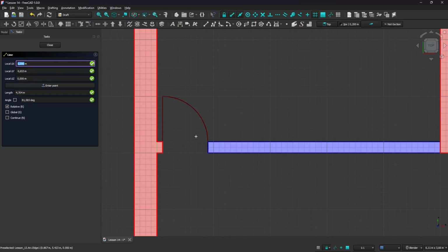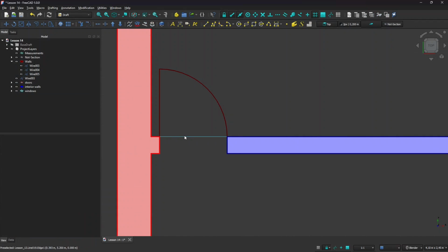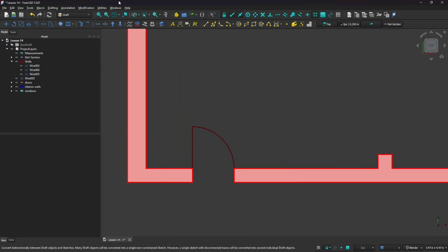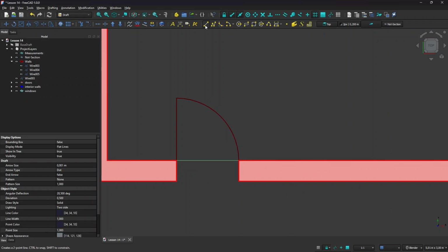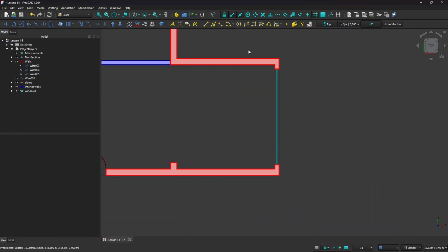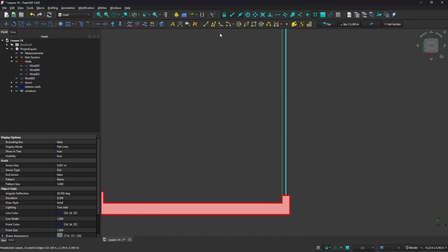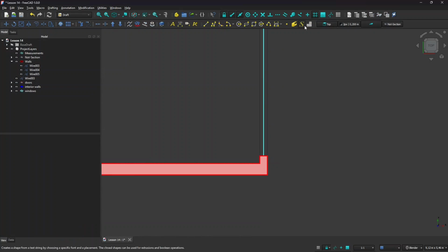And also here, if you change the material of the ground, you need to change here also with the line. So you can also use a hatch here and another hatch here, or a fill here and another fill here. So you may want to distinguish with this little edge. And also when you come inside your house, you're probably going to have here to distinguish the inside and the outside. So that's the edge. And also here, if you have a curtain wall, you're probably going to have something like a mullion or a frame at the bottom, and you can visualize it like this.